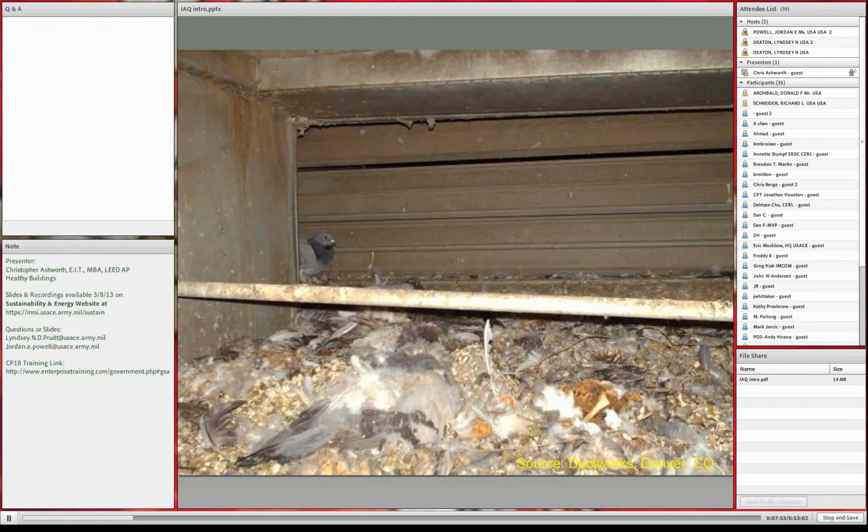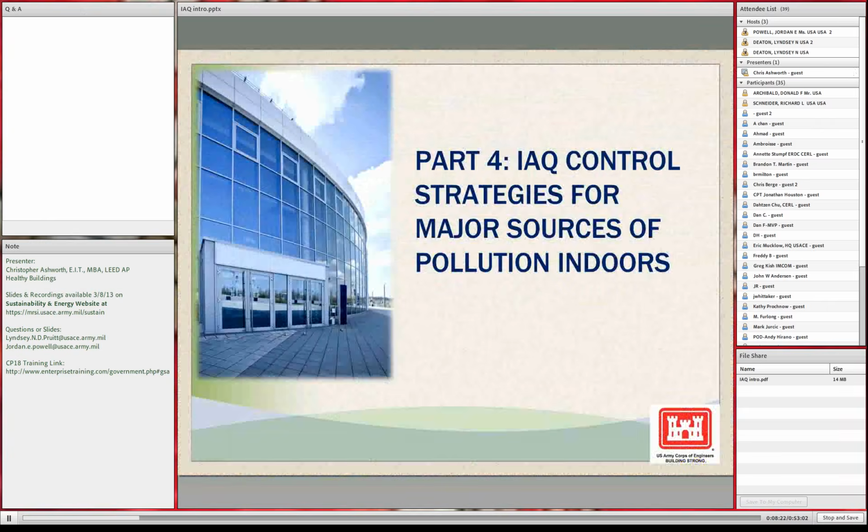Here's a prime example of an outdoor air introduction system that hasn't been maintained properly. Not getting rid of birds' nests, etc. in the outdoor air can obviously, by not fixing the issue, have a large effect on the indoor air quality and the various contaminants and diseases that could run rampant from birds and other random animals. But this is something we see fairly commonly in large cities across the country and across the world. It's a lack of maintenance ability, but not doing preventative maintenance now can really cause issues in the future. And those, again, are just some sample snapshots.